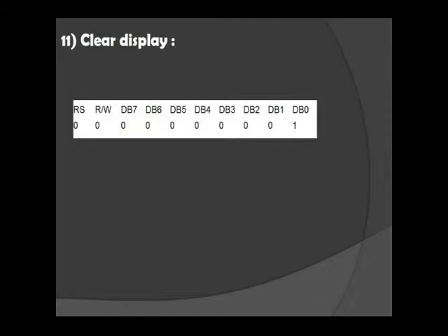Clear display. Clear all the display data by writing 20H to all DDRAM addresses and set the DDRAM address counter to 00H. It returns the cursor to the first column of the first line and sets the entry mode to increment mode.